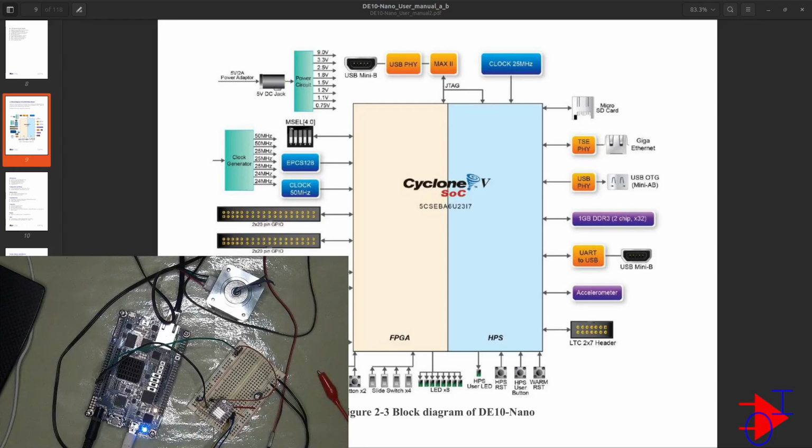So if you look at this architecture, the HPS side has the UART access, so it can directly listen from the UART connection, and there is only one UART. Yes, there's only one UART, the one that we use for the console. So eventually we have to turn off the console to listen in, which we did in the first or second part of this whole series.